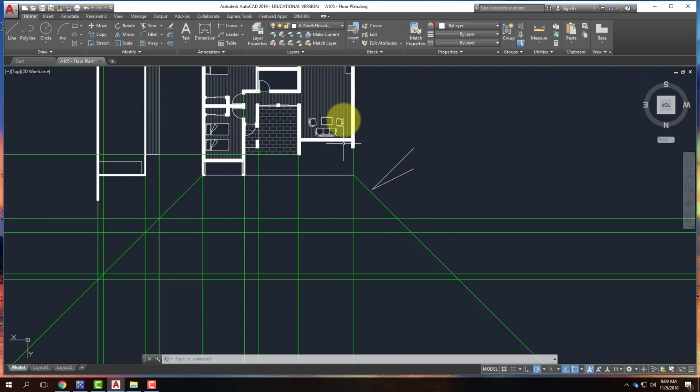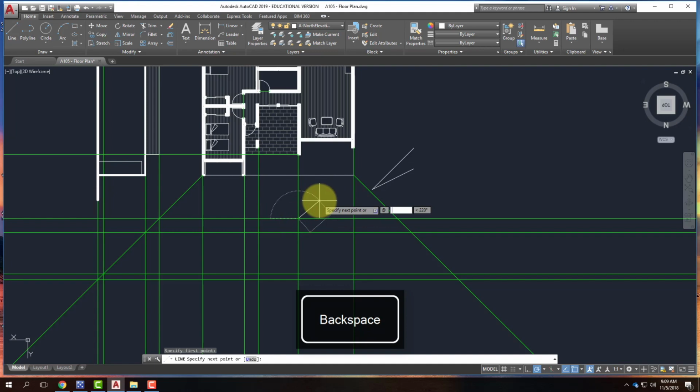So I need to know in this building what I want the roof to look like. This is up in snow country, so in all reality, it would probably be a steep roof. So I'll use a 12 and 12 for right now. So I'm going to start at where I think the top of the roof would be. So in this case, it would be right here. This was the taller section of my roof. I would start right there at that corner.